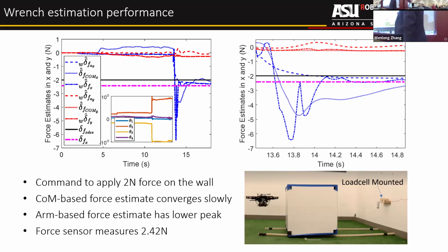It converges very fast. It doesn't overshoot that much, again, because we are just running that at the flexible body here. It doesn't really have that long convergence, but as you can see, it's very difficult to figure out when that contact actually happens by looking at this graph, right? So we basically run a sensor fusion, and this is the line that we get.